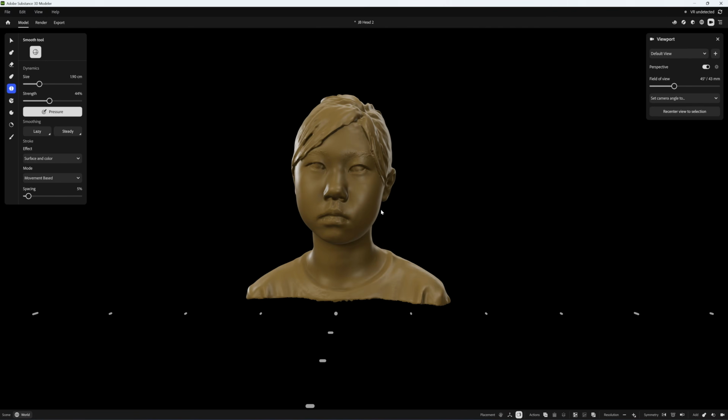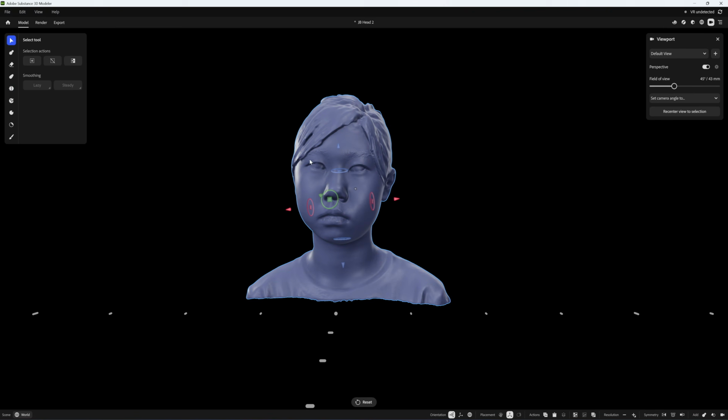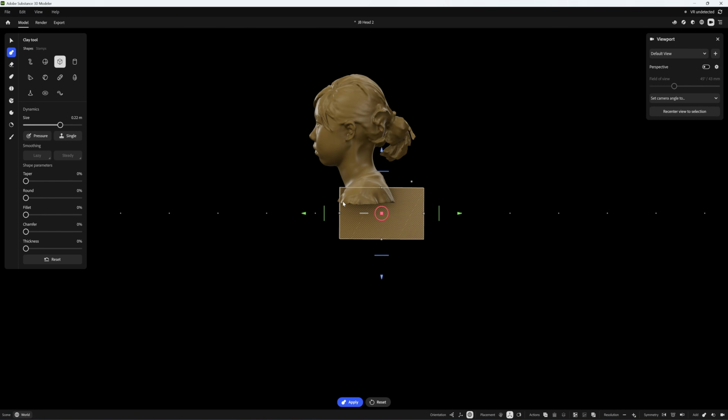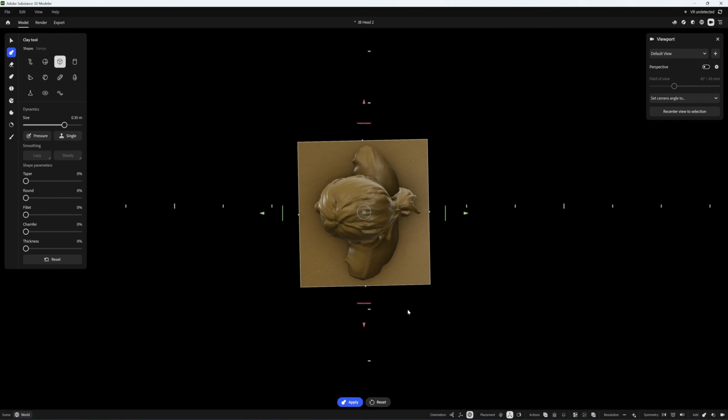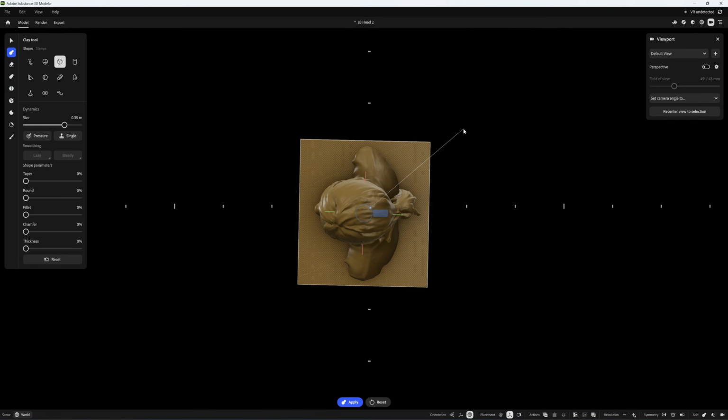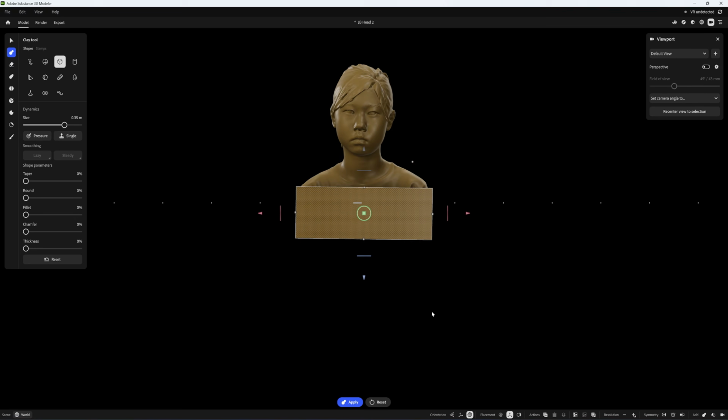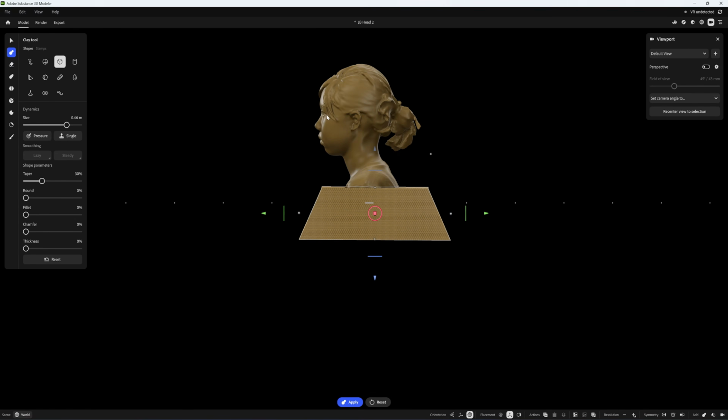That's all. Okay, to be able to print, you need to put this on a stand. I'm going to make a quick stand. Click on the model here. Click on this clay tool. Extend it here. Extend it here. The new box that we add has the same resolution as the model, so it can add into the model automatically. So you can't just make a block like this. You need some style. Create a taper, move it here, and the face is here.